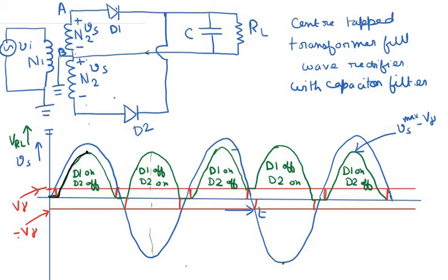When it becomes reverse biased, no current can flow through this diode, so the capacitor discharges itself through this path just as before, and an almost constant voltage across the output is maintained by the capacitor. The capacitor discharges a little bit before charging again, and then it reaches this point here.